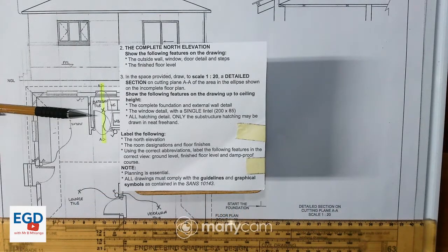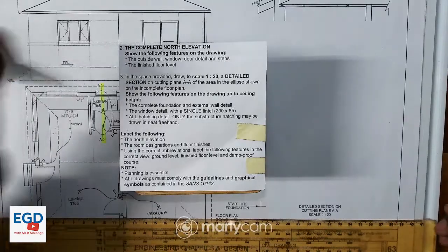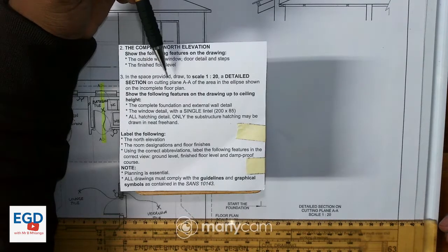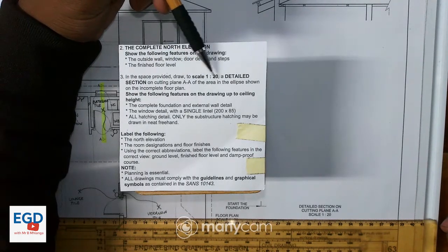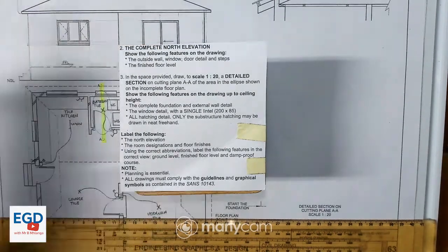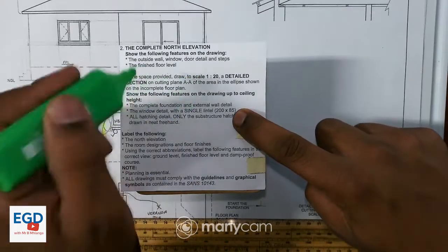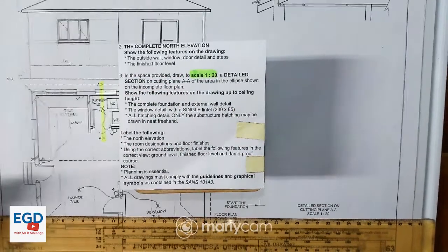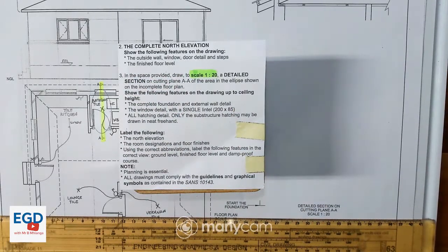Okay, grade 11s. So now I'm moving on to the third question. The third question says, in the space provided, draw to scale 1 is to 20 a detailed section on cutting plane AA of the area and the ellipse shown on the incomplete floor plan, right? Okay, so we've been told that we have to use scale 1 is to 20, right? So we are not using scale 1 is to 50, but now we are using scale 1 is to 20. That means I'll divide all the dimensions by 20, right?